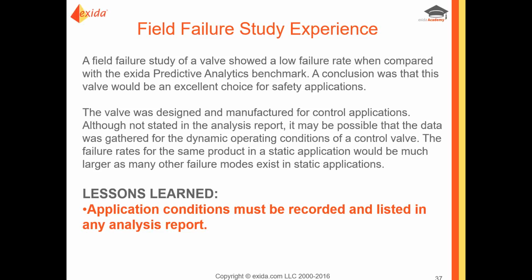I mean, these kind of go on, and I don't want to overdo it, but the bottom line is the field failure study of a valve showed an extremely low failure rate compared to the PA. They were below the outlier limits. And of course, the manufacturer who did this study concluded that this particular control valve would be an excellent choice for safety applications.